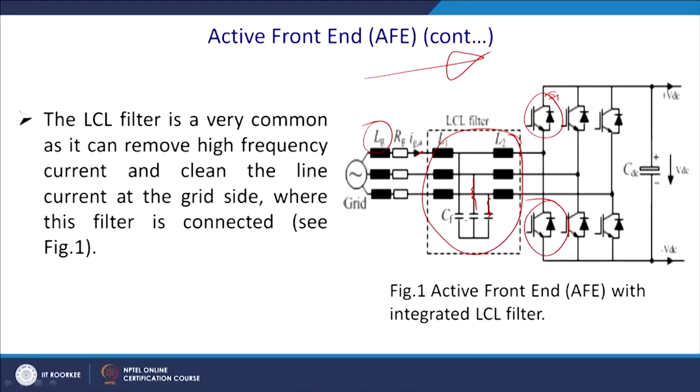Of course, you can damp it. There is a challenge, because you can put a resistance here, and you will find that it has been damped out. But if you provide damping, you will find that your response, or whatever desired THD you want to have, has also come down. So, that is a challenge, and there are many researchers working on the active damping of these LC filters, and you can refer to a paper or you can mail me, I can cite the papers.